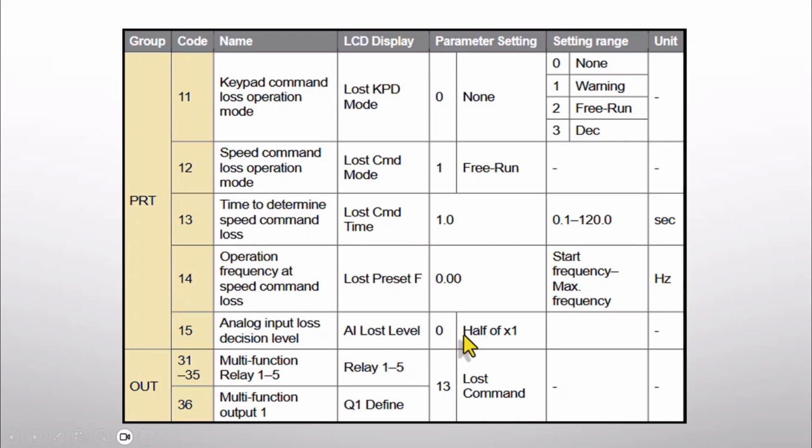One of the experienced technicians explains the configuration process. If you set the initial reference point for the various analog inputs located on the frequency inverter control unit, I will consider exactly 50% of that value. And if that 50% of the value is detected within the system, I will conclude that your analog input has been lost or disconnected.